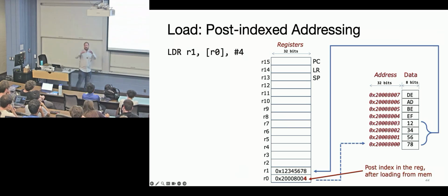But if you are saying I'm going to look at peripheral GPIO port A, well, there's a bunch of registers there. Now all you have to do is say I want to go to register 0, you can just use this address. Then I want to go up to register 4 or register 8 or whatever it is, and you just keep this value in here and you're just moving. All you have to do is manipulate that last little bit, the immediate, to get to that register. So it lets you do offset registering based on some base register, and it makes that easy. The architects know how often that happens. It happens so often, they said, oh, we better give you this functionality.